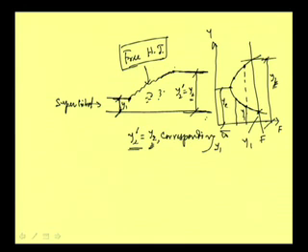Now the question is, what if the tailwater depth is higher than this one? For this y1, the sequent depth y2 is fixed, but the tailwater depth may be more than that, or it may be less than that. Then how will the hydraulic jump occur? We need to understand that, and only by understanding that can we classify the hydraulic jump into other types, that is the repelled jump and the submerged jump.